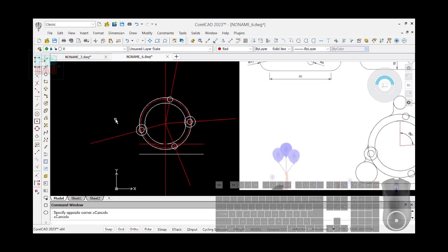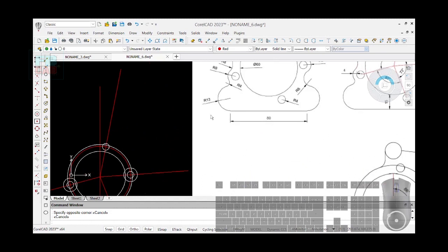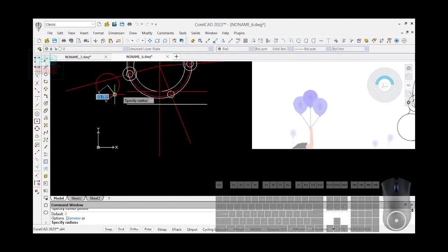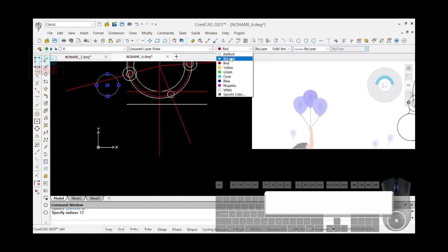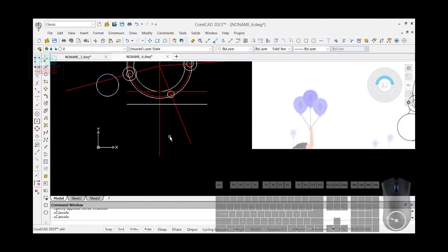Okay. Now, having done that, I have these two circles, whose radius is not given specifically. Here we have 13. This one is not given, so we assume they're about the same. So I want a circle of radius 13. Let me change this to a layer. So another circle. I'm purposely doing this so that we'll see the advantage of constraint. Dimensional constraint radial, 13.